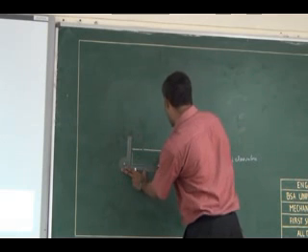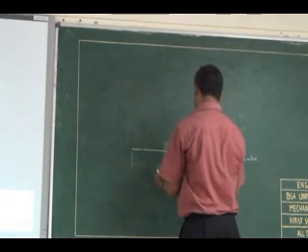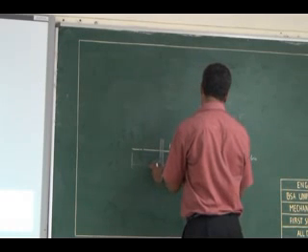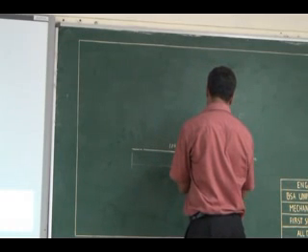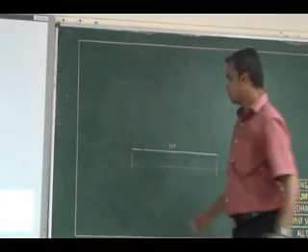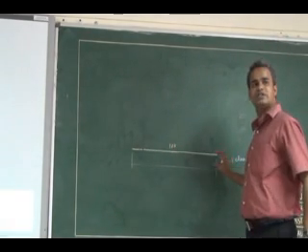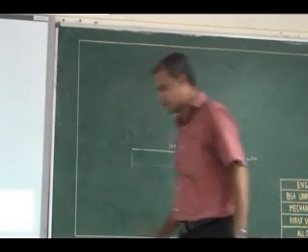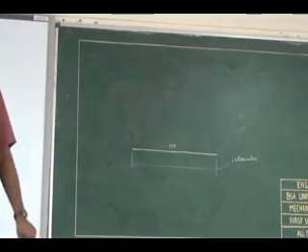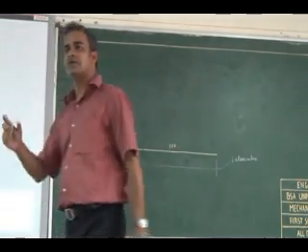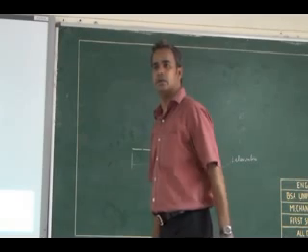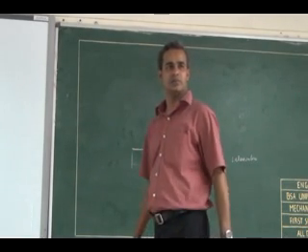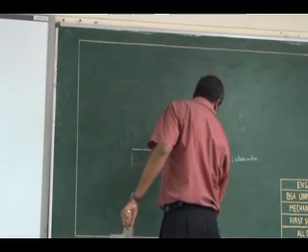You see, it's a parallel line. I can draw it. So this is a dimension line which will have a gap of 10 mm from the object line. It should have a minimum gap of 10 mm. Remember that: each and every dimension line should have a minimum gap of 10 mm. Otherwise it will be wrong dimensioning. So this is called the dimension line.